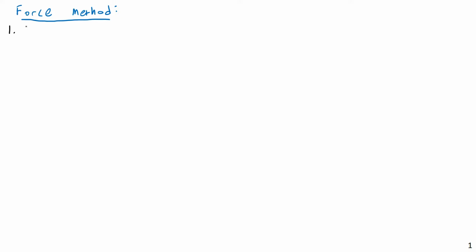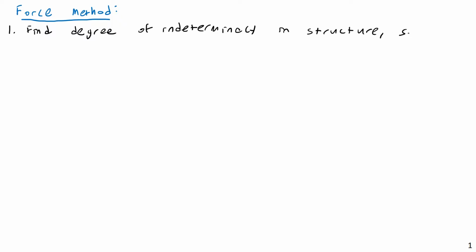So the first step in the force method will be to determine the degree of indeterminacy in your structure and select an equal number of redundant forces.